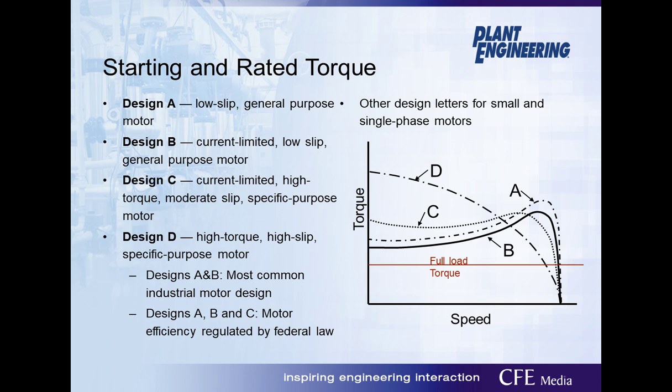Similar to insulation class rating, NEMA and IEC have standardized how we reference the starting current, torque design, and speed or slip of electric motors, those three factors: starting current, torque, and speed. There are many NEMA and IEC design codes, and we're not going to get into the whole alphabet today. We're only going to cover the most common.